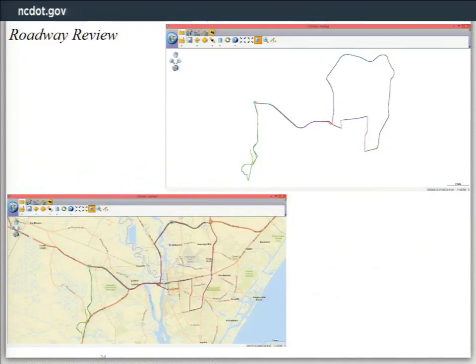So, roadway review. NCDOT conducted a joint research project with NC State's ITRE, the Institute for Transportation Research and Education. Pavement took IRI measurements, or International Roughness Index. The TAA field team surveyed the road with ArcPad to assess the road conditions and rode along with members of the public to conduct an average person's report on the roads. This project was to ensure the NCDOT's assessment is contrasted with a much more qualitative public perception. This project was actually pretty similar to the MCAP program in terms of what data was recorded and contrasted.